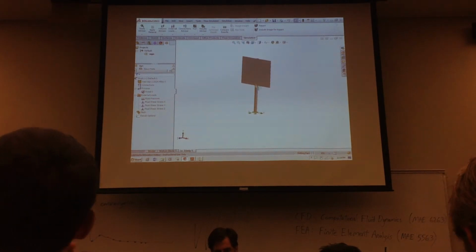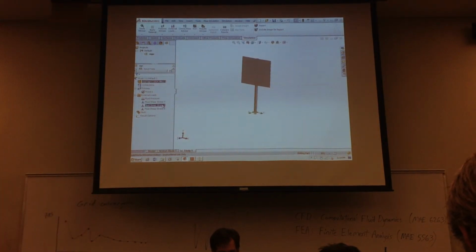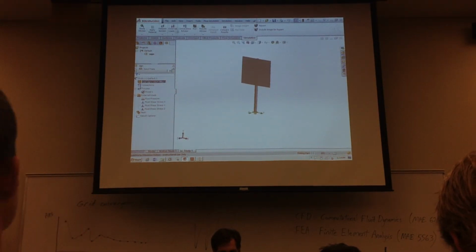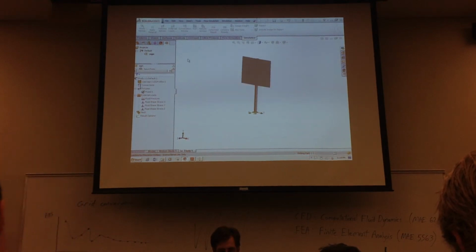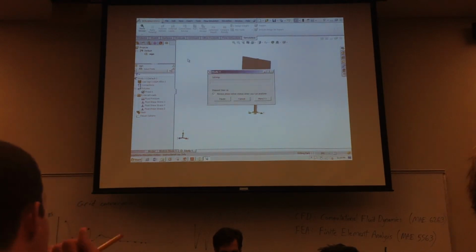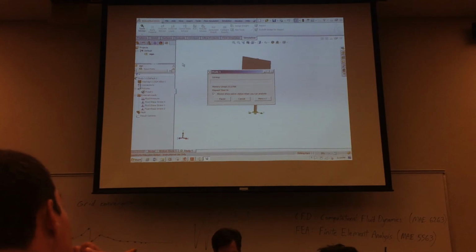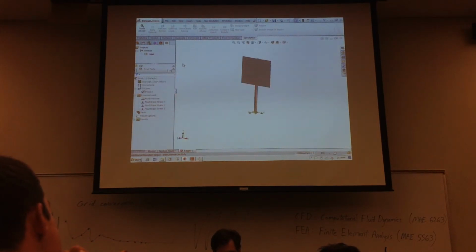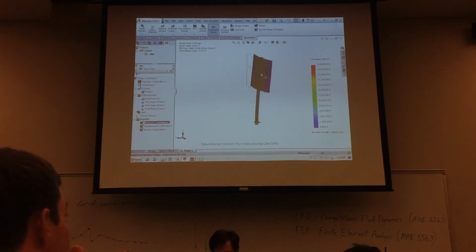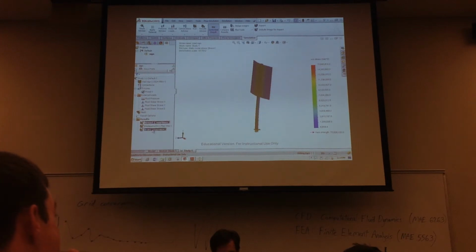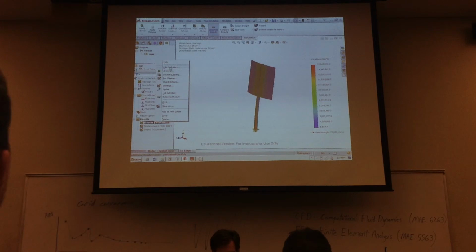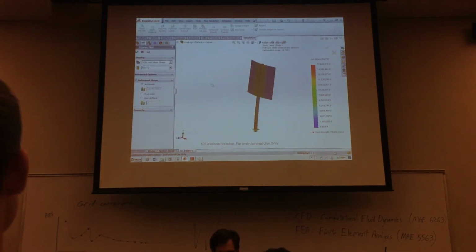Okay, so we've got material, constraints, loads. We're ready to go ahead and run this study. So it will generate a mesh. It will fairly quickly generate results. Okay, so it does these 3 result plots for us. On any of them, you can right-click and do Edit Definition. If you see, this is a stress plot showing von Mises stress.